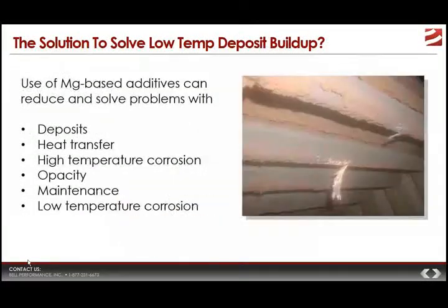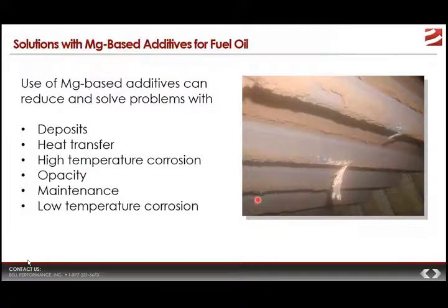Now, if you use magnesium-based additives, you can really have a positive impact on problems like deposits and heat transfer problems. You can really help with high temperature corrosion and low temperature corrosion. You can help with opacity, and you can help with your maintenance.